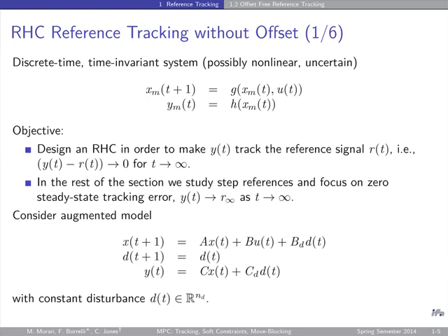If you look at it, these are now my system equations, and one part of the state of my new system is X, and the other part of the state of my new system is D. So X and D is my new state of the system. This augmented disturbance is an additional state that I will estimate through my observer. And this is very common. That's in the lecture that I skipped on day 2, the one on modeling uncertainty.